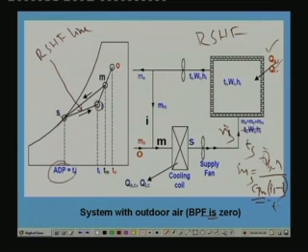Once we know the mass flow rate of the supply air, then again performing latent cooling load balance and the total cooling load balance, we can find out the supply air humidity ratio and supply air enthalpy. So, we can fix the state of the air. And in fact for this simple case, once you locate this point, you can directly read these values from the psychrometric chart.